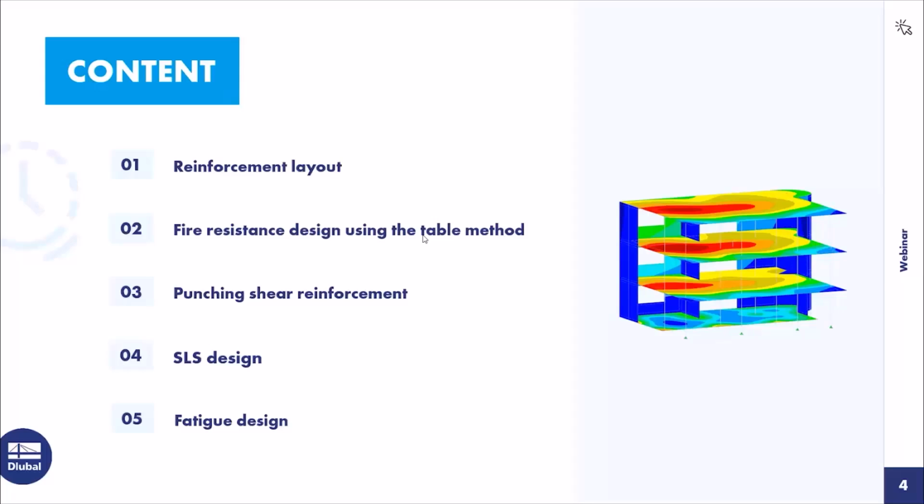Before this feature, we were only able to give the forces and parameters for reinforcement from other firms or so. Now we can model this reinforcement type, and you can calculate your punching shear design completely with RFEM 6.